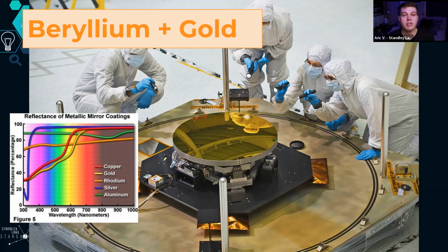So every material that has a thermal change will also shrink or grow depending on this. Think of power lines sagging in the summer heat or tightening up in the cold. All materials do this to some extent. Beryllium does that relatively little, but when we're talking about a drop of close to 300 degrees total, about 250 Kelvin, it has to be machined a little bit larger.